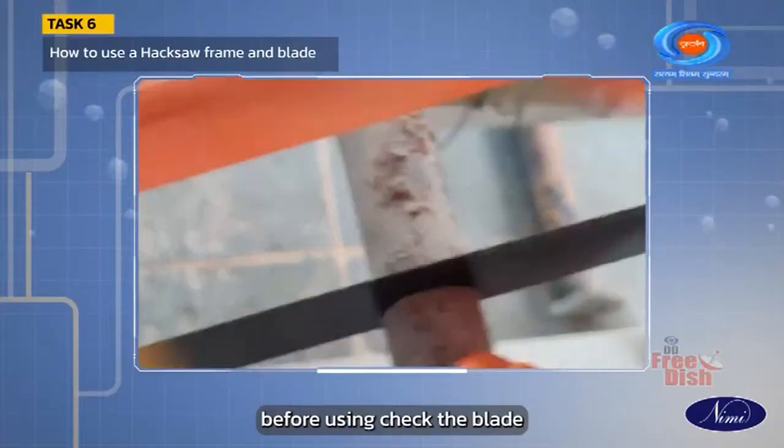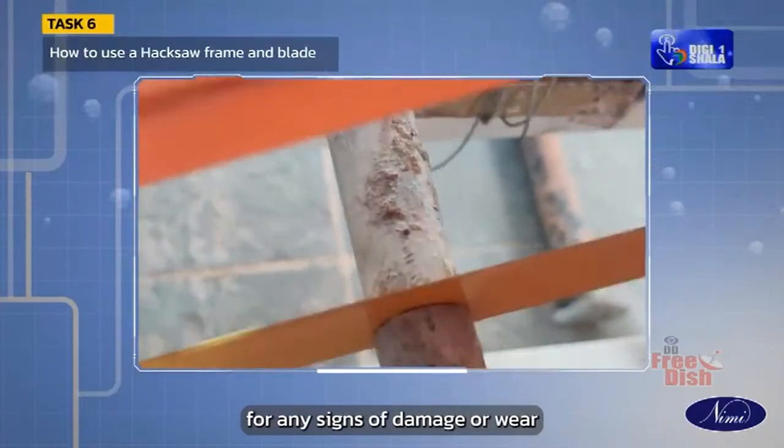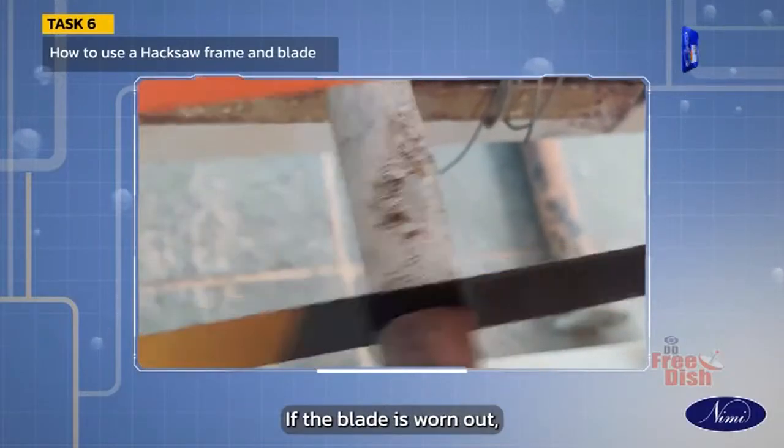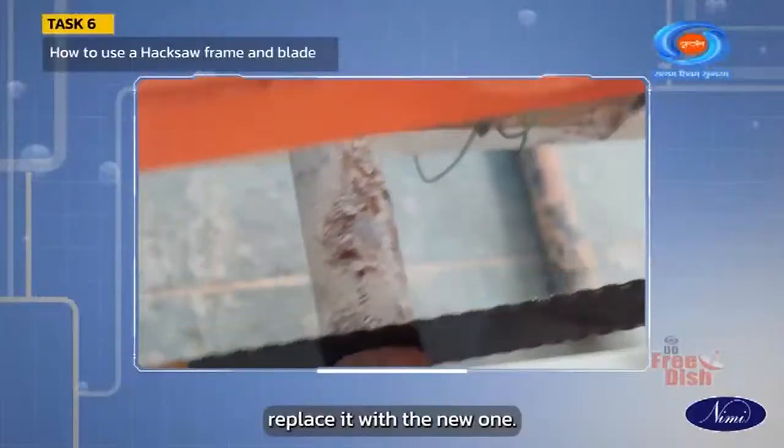Before using, check the blade for any signs of damage or wear. A damaged blade can compromise safety and efficiency. If the blade is worn out, replace it with a new one.